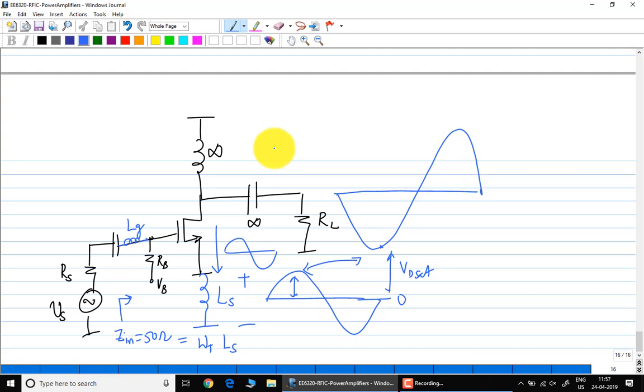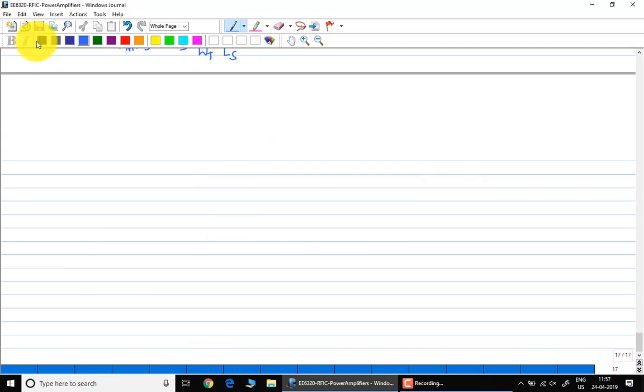I told you cellular requires watts, right? There is just no way of getting out watts of power from a CMOS PA very reliably. Okay, a lot of people have tried and failed. So it doesn't make sense to do all of this, right? Why add 2 more inductors, do all of this? It is just a lot easier to do something like this.